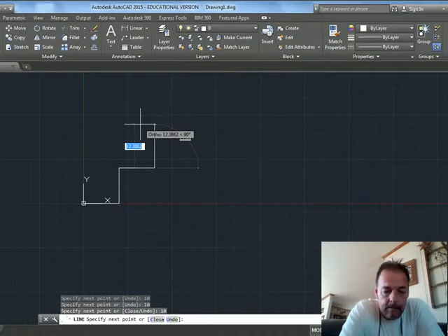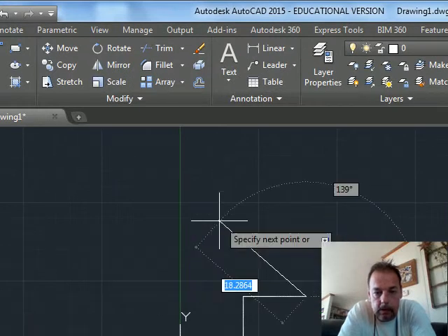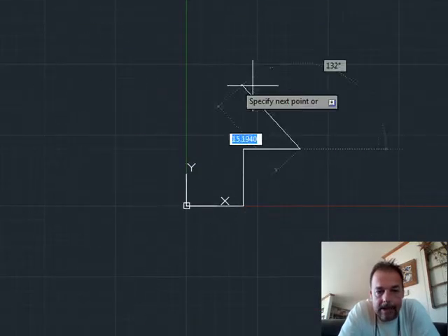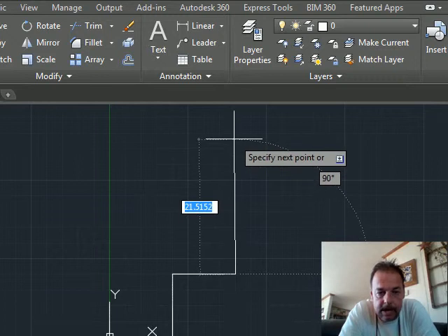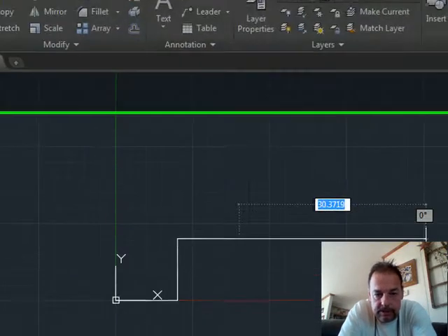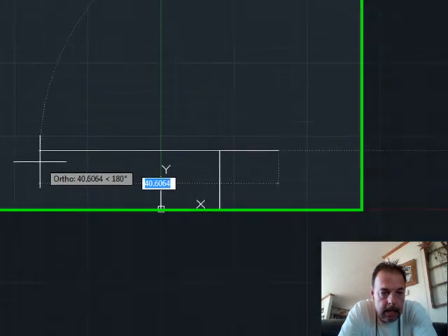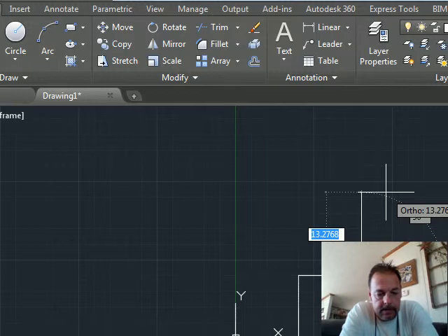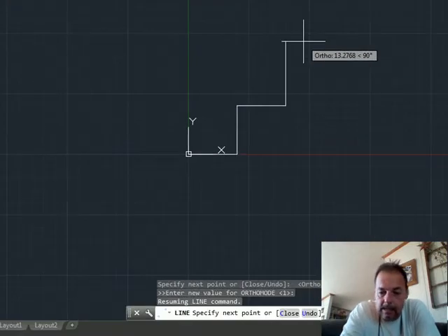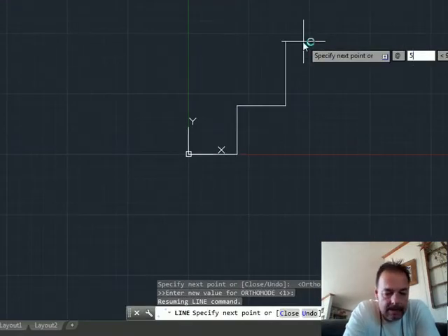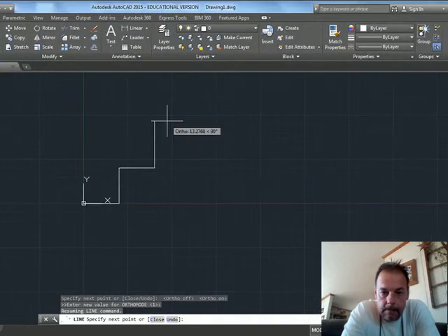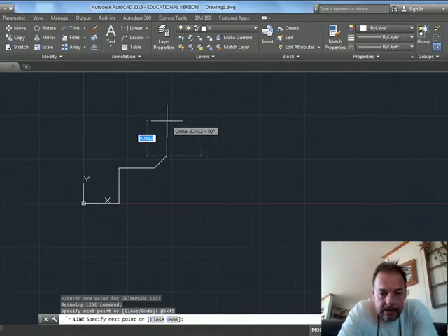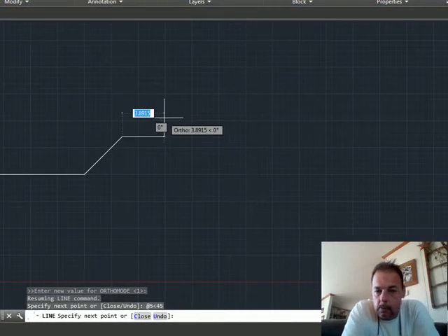There's two other ways to enter in geometry. If I take my F8 off, I can go ahead and go in angles. Remember that AutoCAD draws, this is 0, this is 90 for AutoCAD here. This is 0 for AutoCAD. This is 270. This is 180. So say I want to draw a 45-degree line at 5 inches long. I can do my shift and say at 5, and there's a little less than symbol. If I go shift and angle, and I want to go at 45, okay, I just drew me a line at 45 degrees at 5 inches.